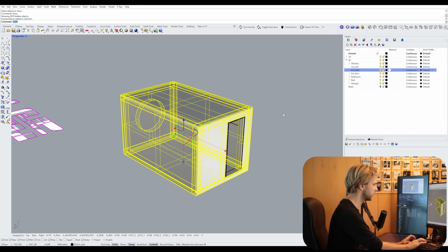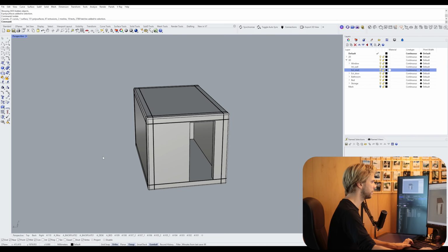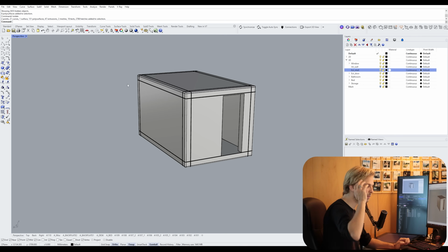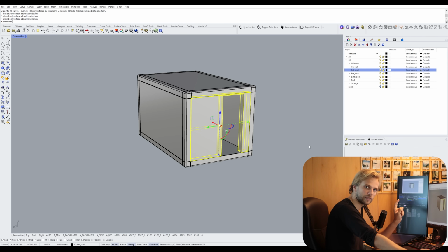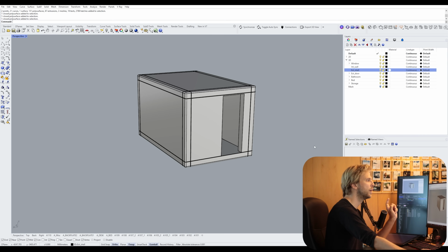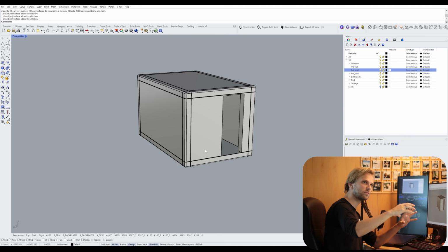So select objects, isolate, only get the objects that we need to unwrap, and remember, every single object right here was unwrapped individually, meaning that the sizes between them are not respected. We can't have that. We need all of the sizes of the islands to be in relation to one another, right?